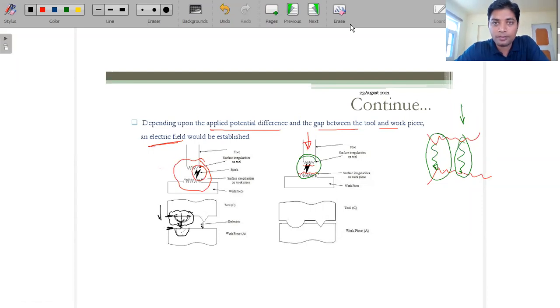Yes, Aman. We need a smaller shape than the shape we need, because we need to keep a minimum distance on all the surfaces. So we have to make the die smaller than the actual shape.